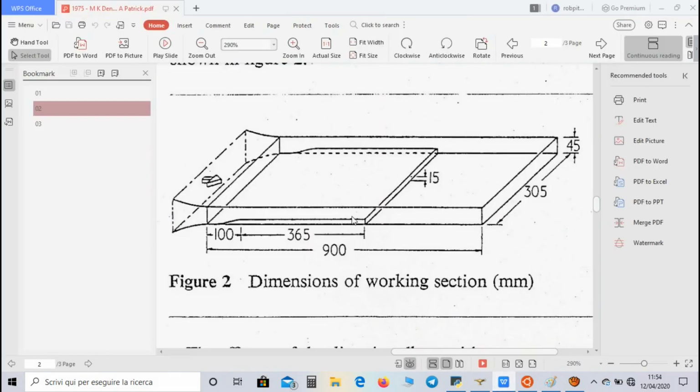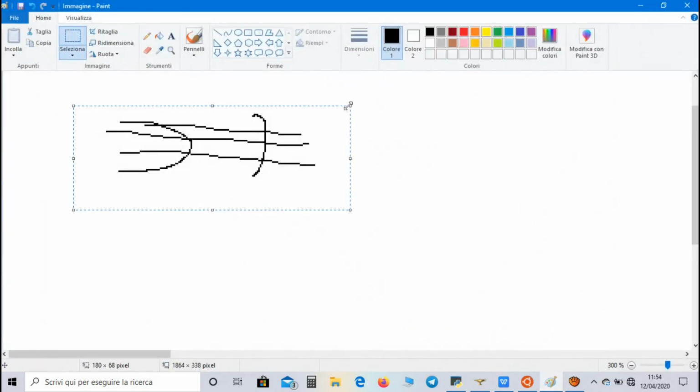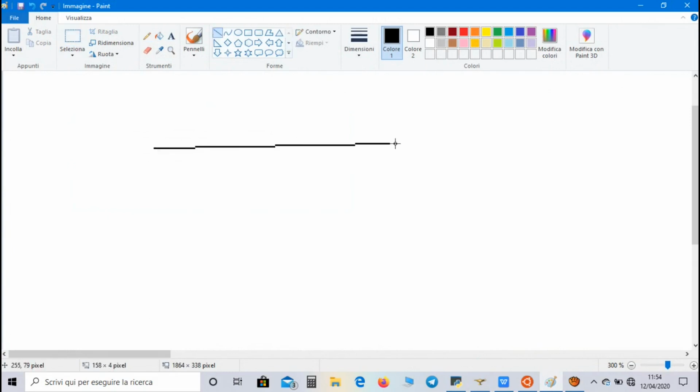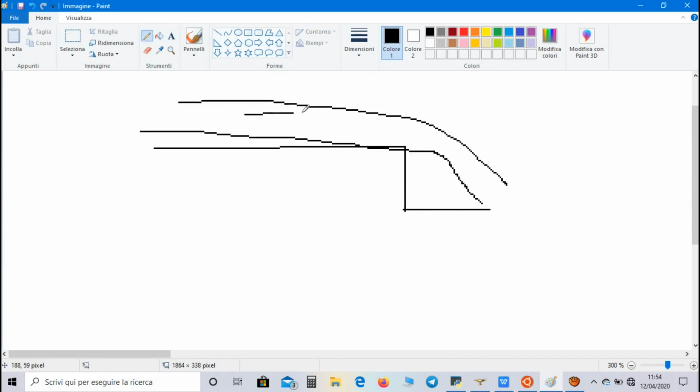For our case, we will create this two-dimensional domain, and we have to pay attention to this step, because when a flow reaches a step, there will be the detachment of fluid streamlines, and near the step there will be the formation of a recirculation zone where eddies move in the opposite direction of the fluid. Moreover, if we plot the velocity profile near the step, we can notice the formation of an inflection point which fades as we move away from the step.